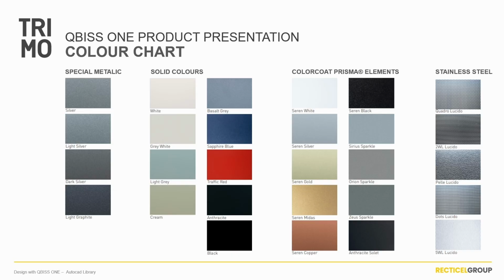We define type of coating project by project. Only pre-painted steel sheet with the best protection on the market is being used to produce the qbiss.support facade elements. The external side, so the one that is exposed to the environment, of the qbiss.support element is protected with polyvinylidene fluoride or polyamide modified polyurethane protection. For the most optimal results, we can adjust protection of the element's internal side based on the building purpose.